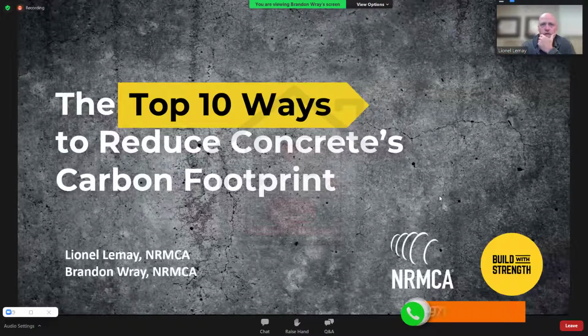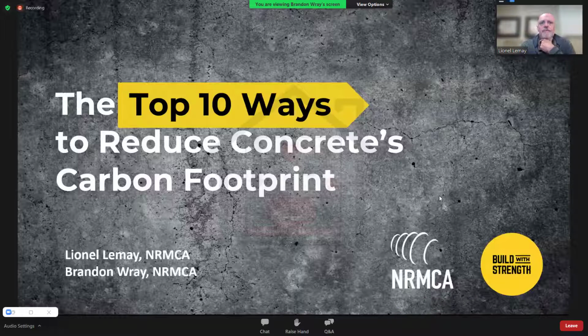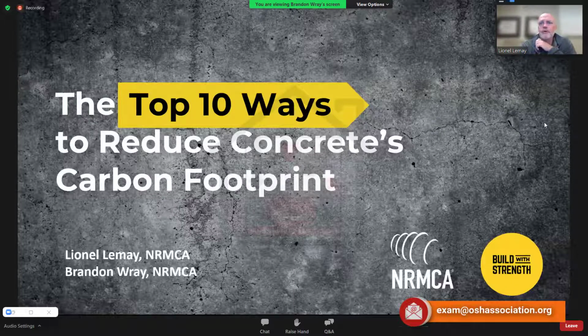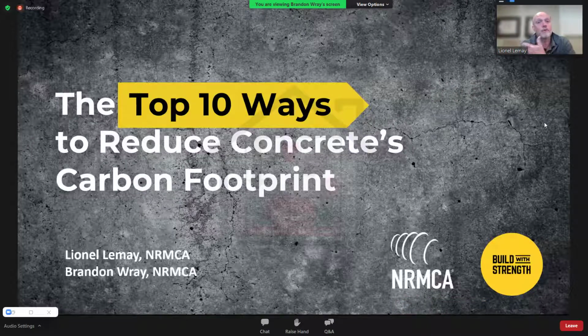So for those of you not familiar with post-tension, a structural engineer needs something like 5,000 PSI at 28 days for design strength, but a contractor, to maintain a schedule, will usually ask for concrete to be 3,000 or 3,500 after 3 days or 2 days, just so that they can post-tension that slab.